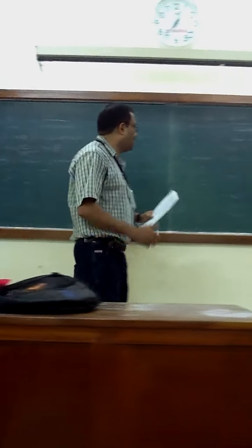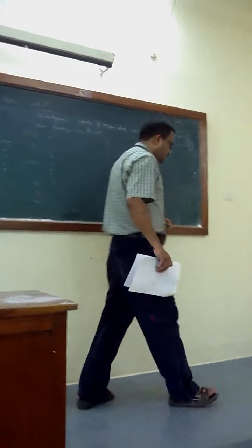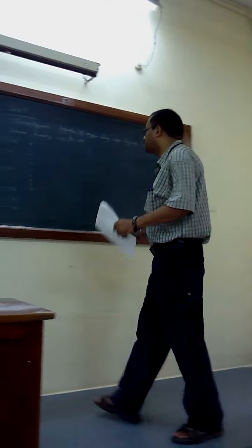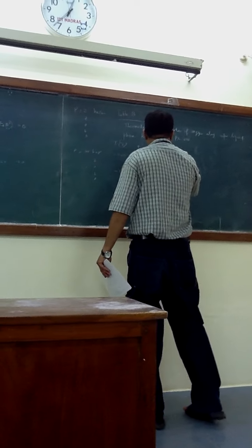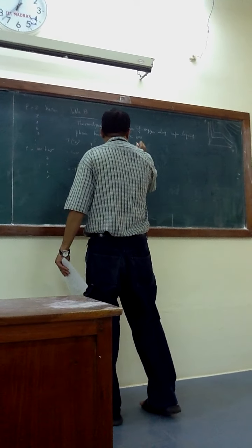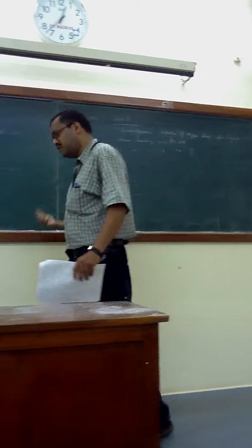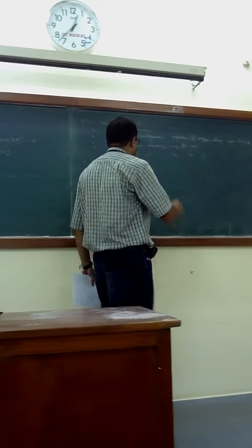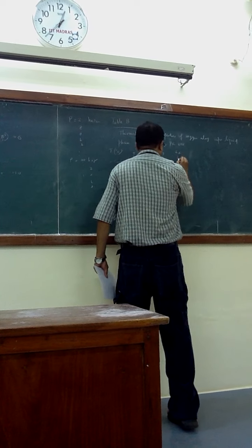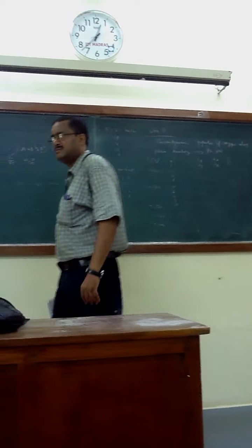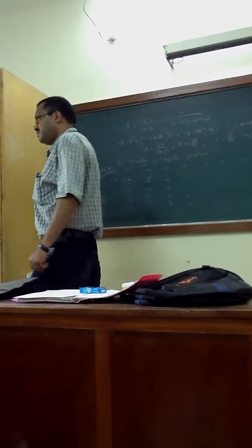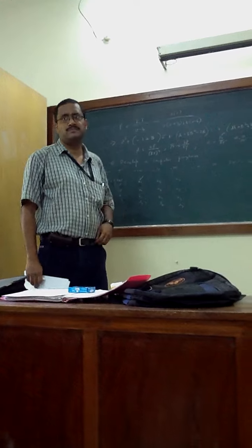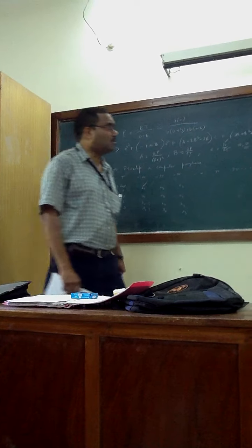So from here we can actually calculate. If there are two roots, you can calculate ZG and ZL. The highest will give ZG, the lowest will give ZL, and that will give you VG and VL, at the particular pressure. You may miss it out.